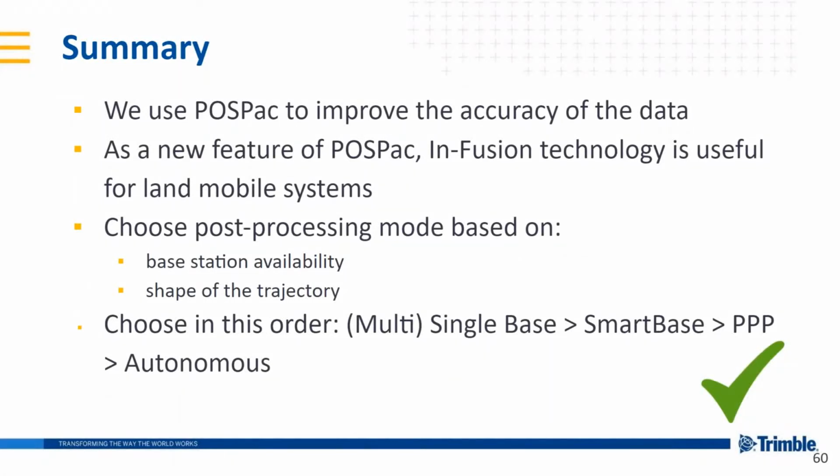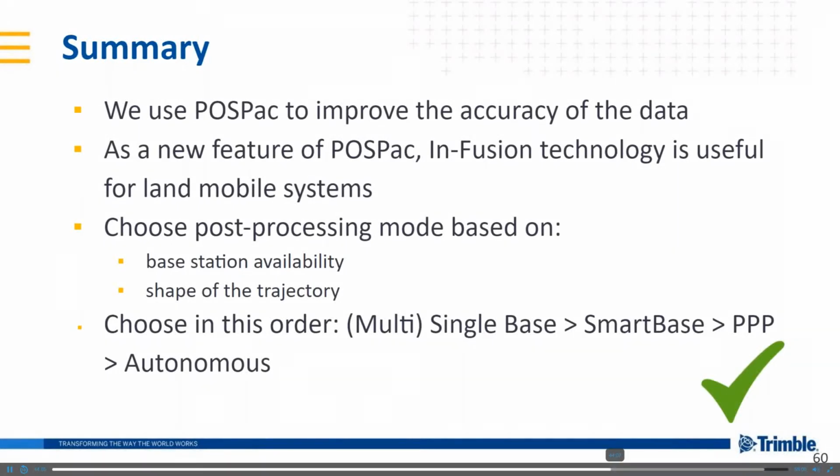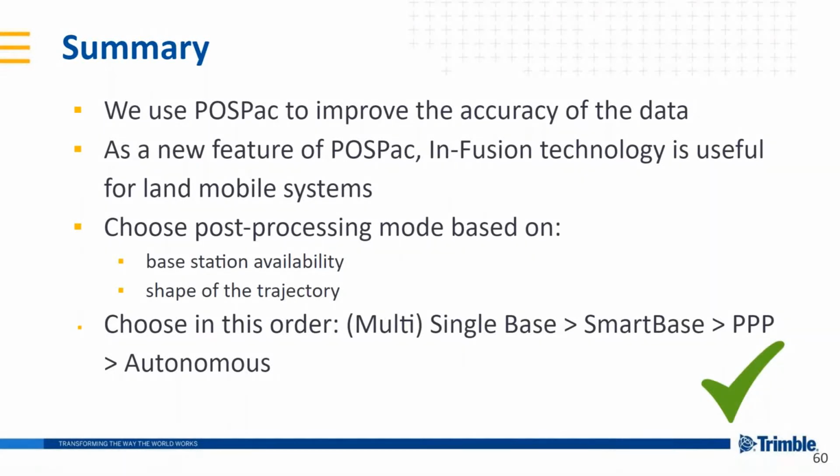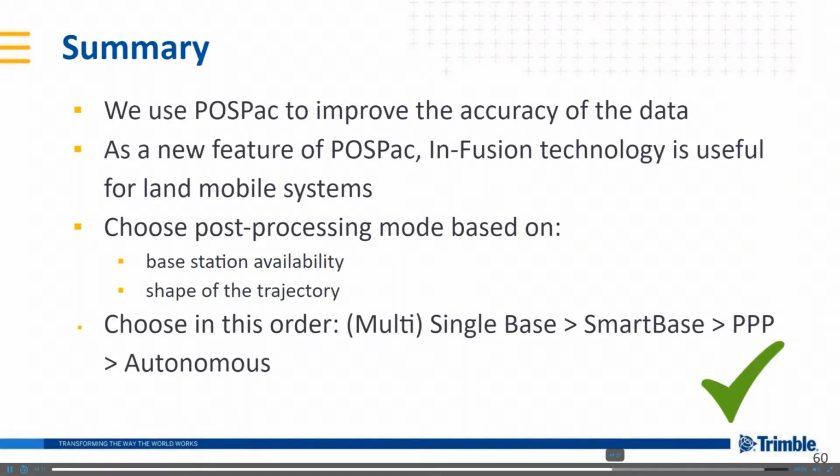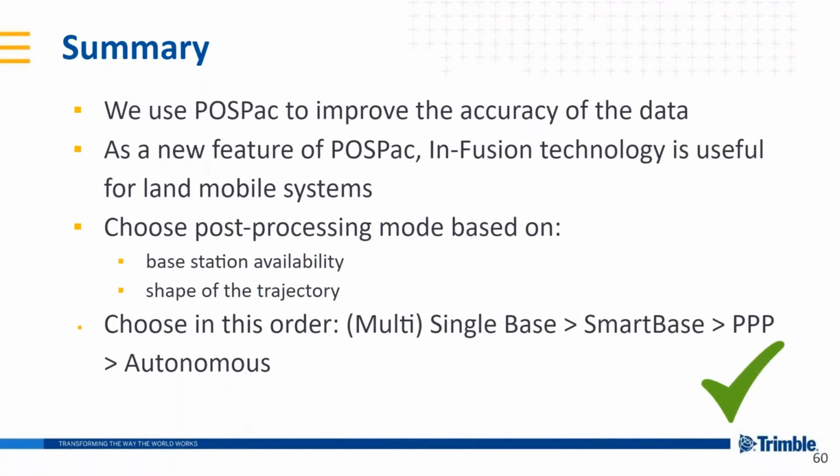Infusion tightly coupled processing mode is recommended for our land mobile systems. Based on this, single base or multi-single base and the SmartBase are recommended over the PPP and autonomous.